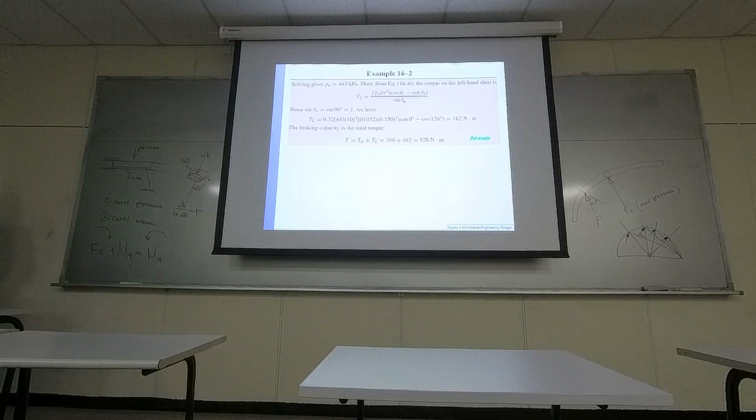So if you have this kind of geometry for braking, now you know the torque generated on both sides will be different. That implies the wear of the brakes on both sides will be different as well.